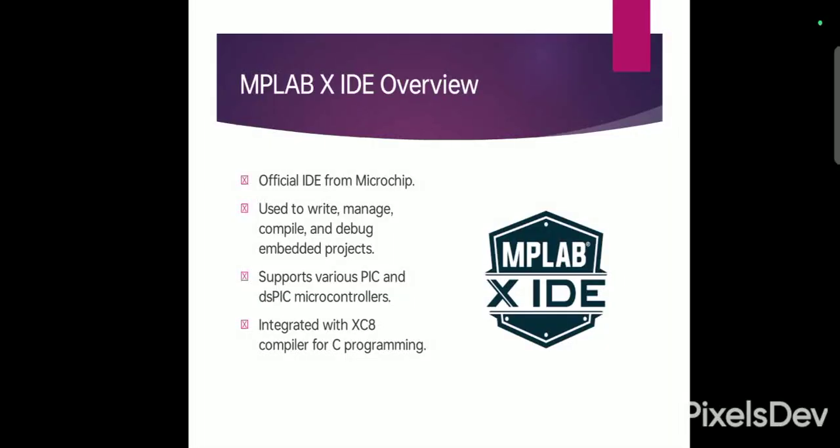MPLAB X IDE overview. It is an official IDE from Microchip. It is a development environment provided by Microchip. It supports various PIC and dsPIC microcontrollers. It allows writing, editing, compiling, and debugging embedded code. It also integrates smoothly with the XC8 compiler.